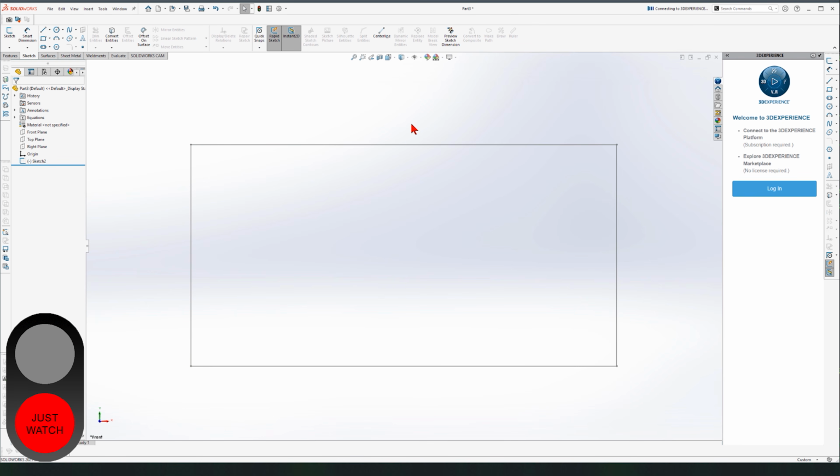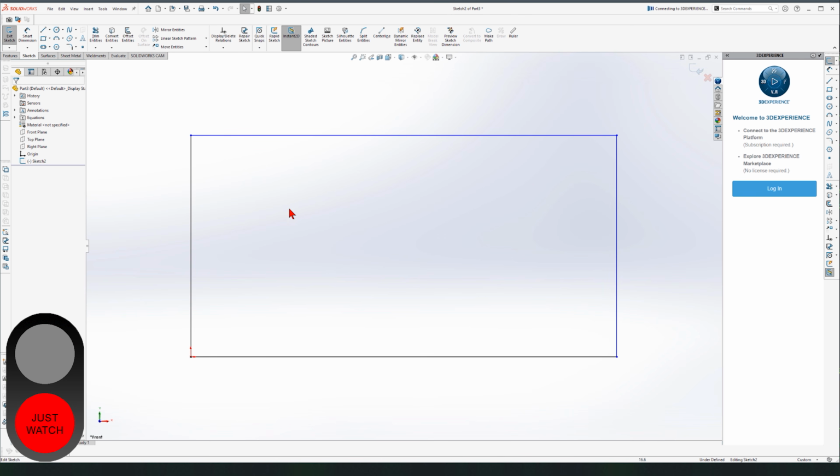Double click away to exit it. Double click on the sketch to enter it. Double click to exit it. Double click on its line to enter it. If none of these works for you for whatever reason, you still have the standard way of doing so, which is clicking on that sketch on the design tree. Then this pop-up appears with a few options. This option inside that pop-up reads edit sketch. Then we enter it again.